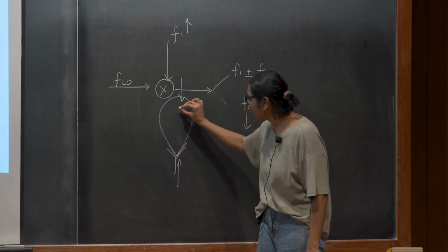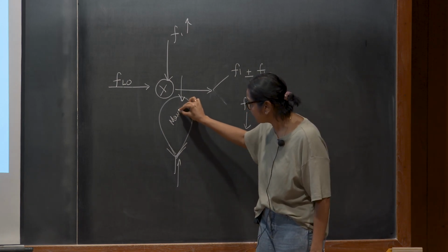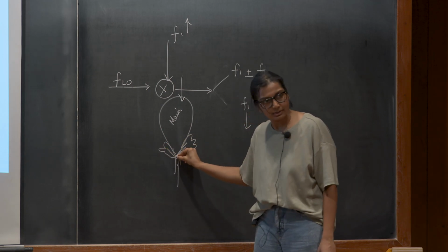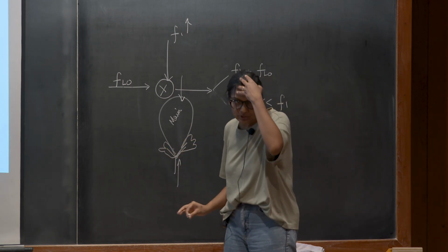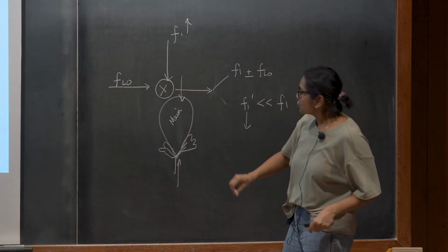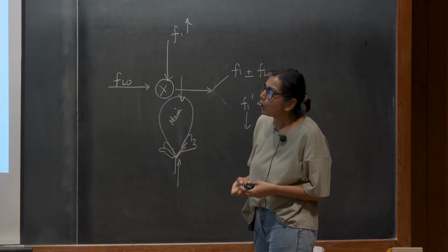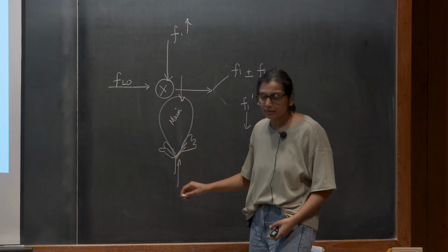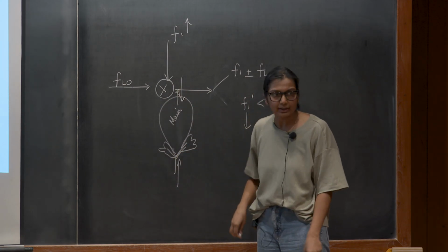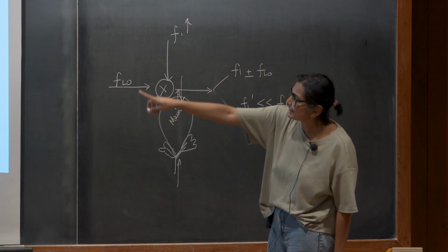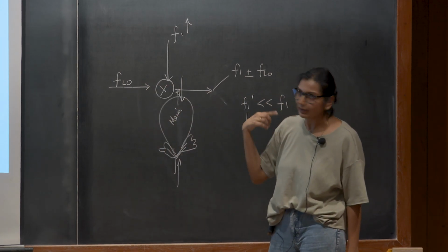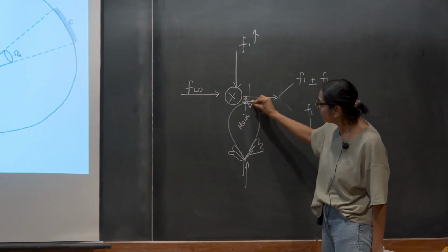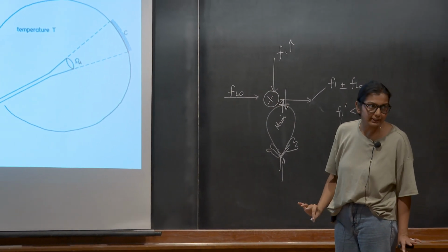And maybe it has, this is called the main lobe because clearly it's nice and big. It could have some funny things on the side, these are called side lobes. So all of these are properties of the antenna pattern. So when I actually make a measurement, this pattern has a peak value. I can take the beam pattern, which is basically a function of theta and phi, and I can normalize it by this maximum value and I get something called a normalized antenna beam.